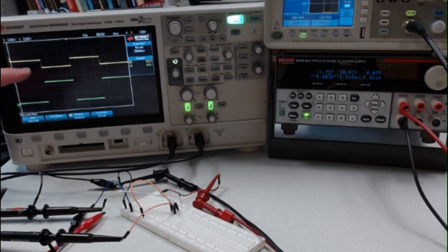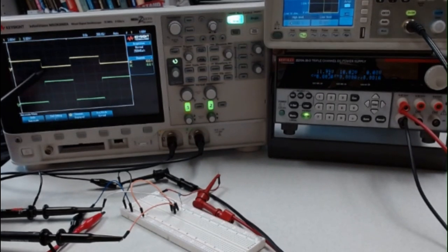Now this is acting as a switch. So this one is turning off and this one is turning on. This is my input. It's between 0 and 5 volts, and this is 2 volts per division, so we're a little less than 2 volts input. So that's coming in from our signal generator, and this is going out from our output. When this one turns off, this one turns on, so it's 180 degrees out of phase.